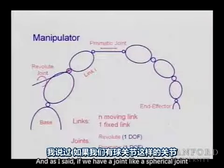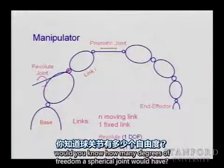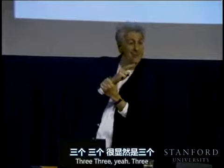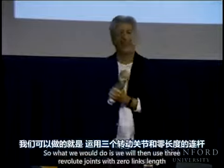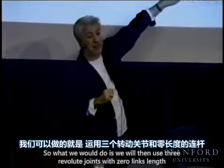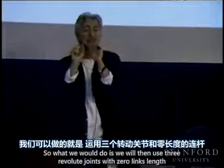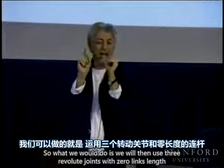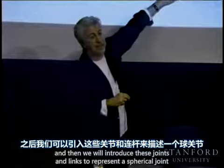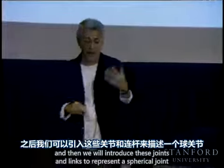And as I said, if we have a joint like a spherical joint, would you know how many degrees of freedom a spherical joint would have? 2? 3, yeah, 3. So what we would do is we will then use 3 revolute joints with 0 length, and then we will introduce these joints and links to represent a spherical joint. Okay.